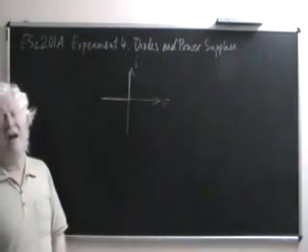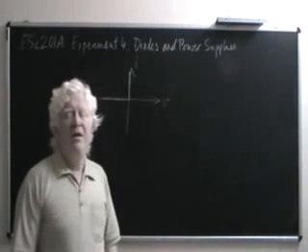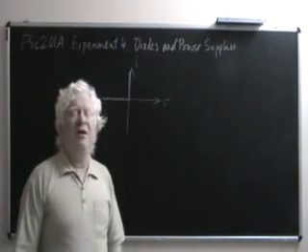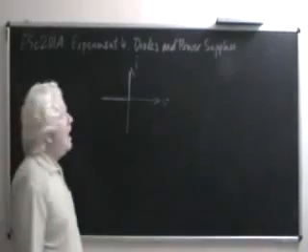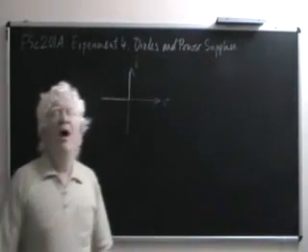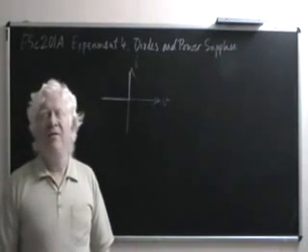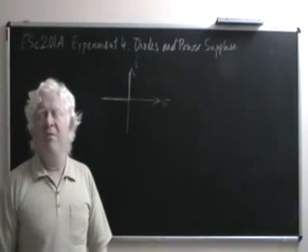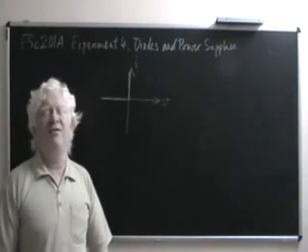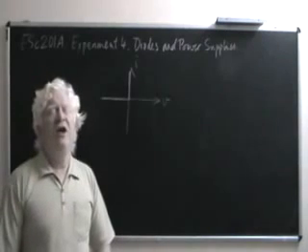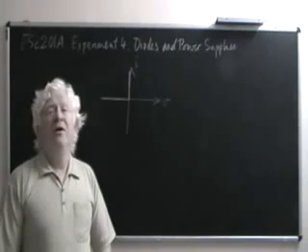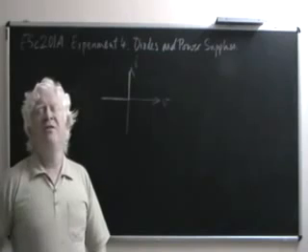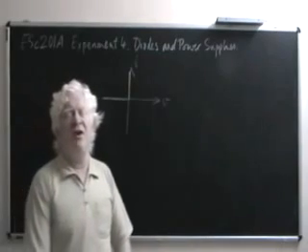A practical diode does have a small amount of current even when a reverse bias is applied, even when a reverse voltage is applied. And that in fact flows until a very large reverse voltage is applied, when the diode breaks down and allows a lot of reverse current. But that happens only once in its lifetime, for the last part of its life. So we are never supposed to apply a very large reverse voltage to the diode. Whatever voltage we apply should be within what is called the peak inverse voltage rating of the diode.